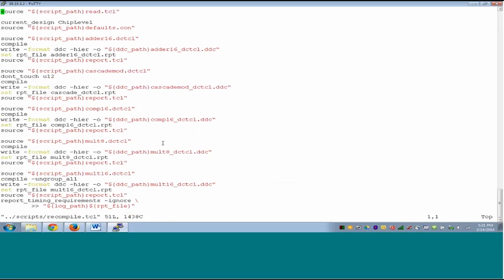Recompile, obviously there it's reading RTL. Now we start from the RTL. So see now the first pass you had your own estimated input output delay and environment conditions for each design. After characterize you get more accurate numbers, and now you want to start from RTL, not from the netlist. It's always better to start from RTL.